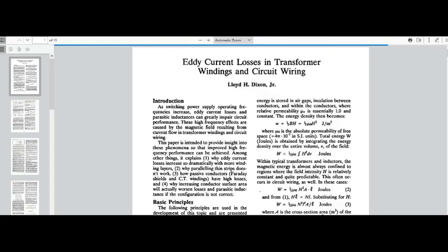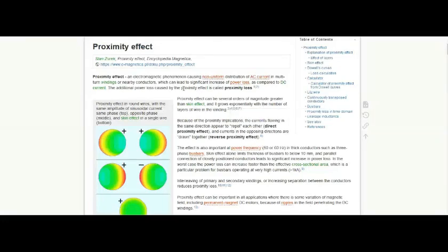And he mentions another thing that is not in this write-up, which I found interesting: in terms of proximity effect, if you use Litz wire, which would reduce the skin effect, the Litz wire is actually viewed as multiple potential places to interact, and it actually aggravates proximity effect.